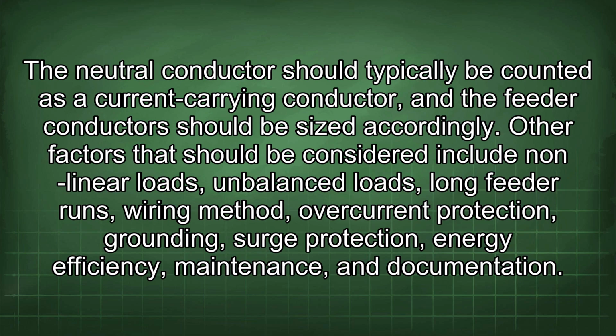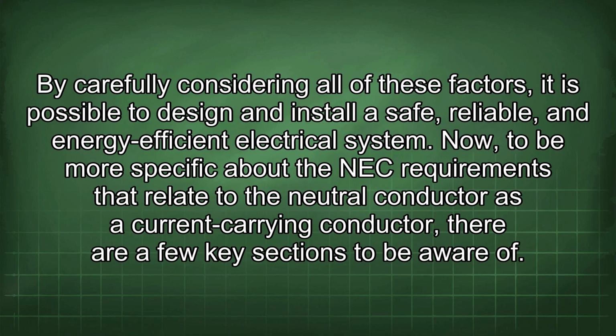Other factors that should be considered include nonlinear loads, unbalanced loads, long feeder runs, wiring method, overcurrent protection, grounding, surge protection, energy efficiency, maintenance, and documentation. By carefully considering all of these factors, it is possible to design and install a safe, reliable, and energy-efficient electrical system. Now, to be more specific about the NEC requirements that relate to the neutral conductor as a current-carrying conductor, there are a few key sections to be aware of.